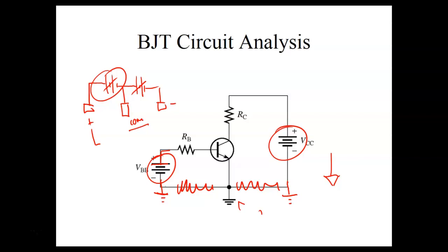So what that symbol does is represent a wire. And I've seen this on some of y'all where you'll have a resistor hooked up to a trainer, and you'll have your resistor hooked up over here, and over here you'll have something applied, and you just leave that one hanging out in the air. And then they'll say, is this right? I said, no, what's that resistor connected to? You know, knowing the difference between series and parallel.